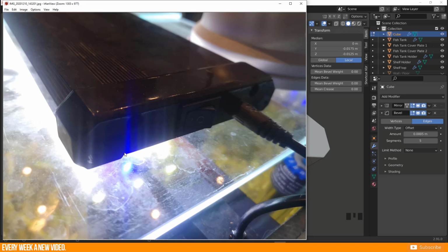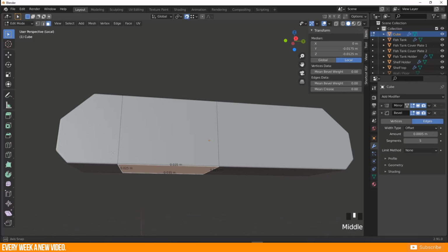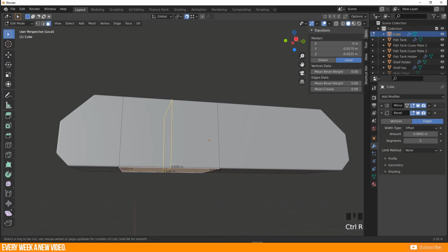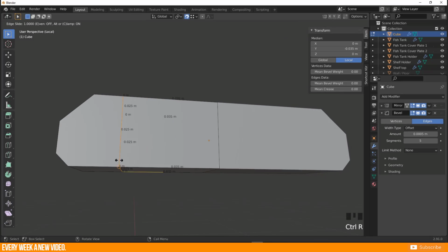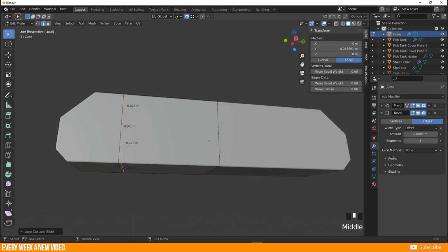So we just are able to add another edge loop and pull this edge inside of here. So when I press Ctrl R to make this, probably I shouldn't snap it currently, so I just disable this and pull it somewhere here. I think this is totally fine.